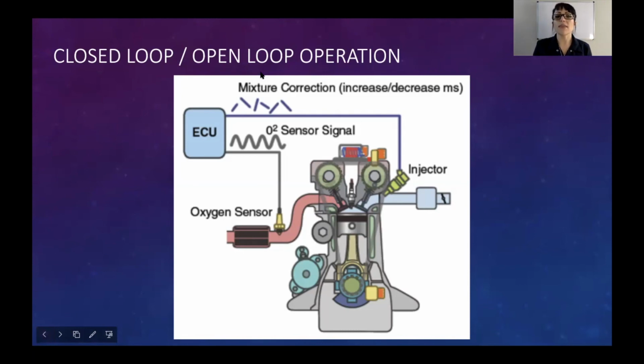So, the reasons why the engine would go into open loop. First one is wide open throttle, because at wide open throttle you're getting max air, so you need max fuel, right? So it doesn't care if it's dirty or not, because that's what the O2 sensor is there for. It's there for engine management, but it's also there to make sure we're doing things clean and environmentally friendly. Well, when you're at wide open throttle, the PCM's like, we don't care about being clean. We need to give the customer what they want, within reason, of course.